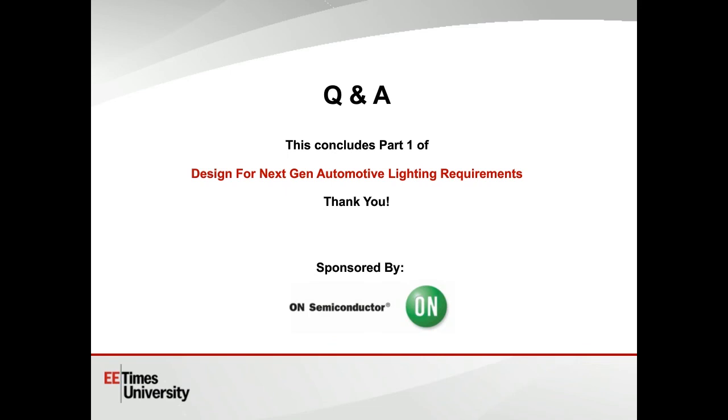The simplest way is just with a resistor in line, but for more sophisticated controls, especially when we start talking about dimming, we need a much more semiconductor-intensive way of controlling them, DC to DC. Again, this is something for Day 3. We'll discuss the various LED drive circuits and their advantages and disadvantages for this particular application.